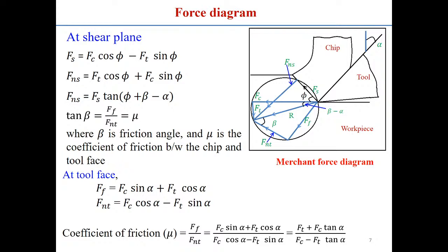The shear force means the force acting on the shear plane, the plane where the shearing happens, Fs. And the corresponding angle, the shear angle, is also given. And the cutting forces we represent as Fc and Ft. There are two components. Fc is the cutting force, which we define in the direction in which the tool is moving.